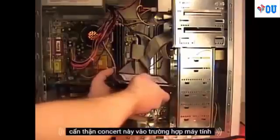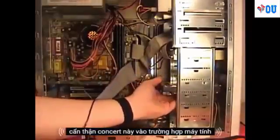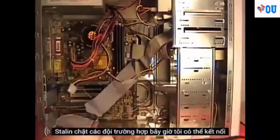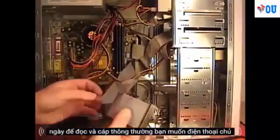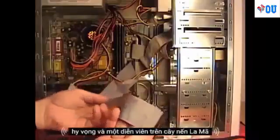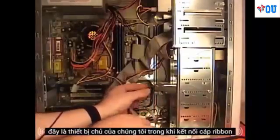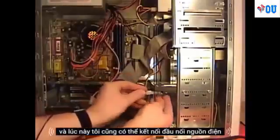Carefully insert this into the computer case and then install the case screws to hold it in place. Installed and fastened the case screws. Now I can connect the data ribbon cable. Generally, you want the master device hooked to the end connector on the ribbon cable. This is our master device, so I'll connect the ribbon cable. And at this time I can also connect the power connector.